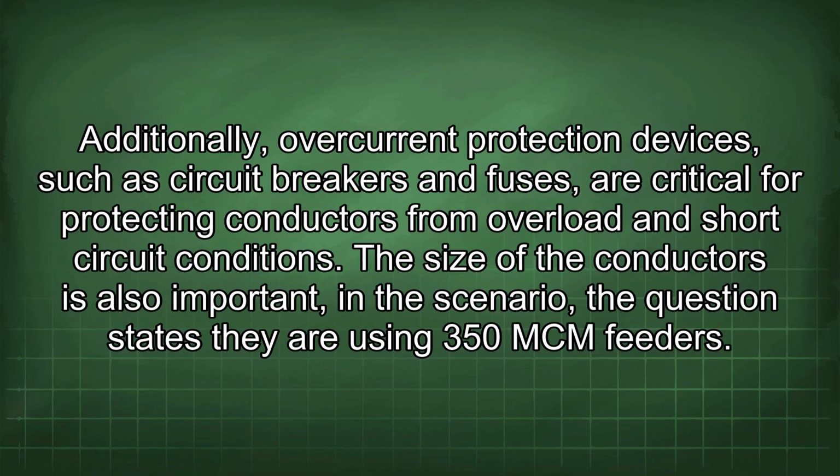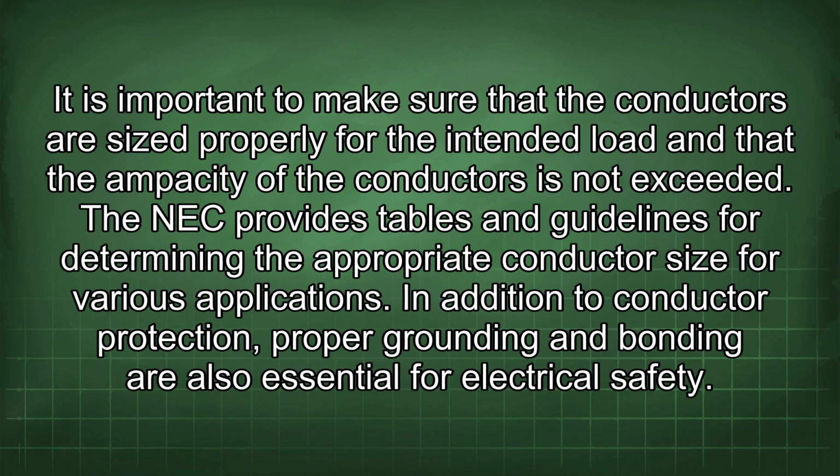The size of the conductors is also important. In the scenario, the question states they are using 350 MCM feeders. It is important to make sure that the conductors are sized properly for the intended load and that the ampacity of the conductors is not exceeded. The NEC provides tables and guidelines for determining the appropriate conductor size for various applications.